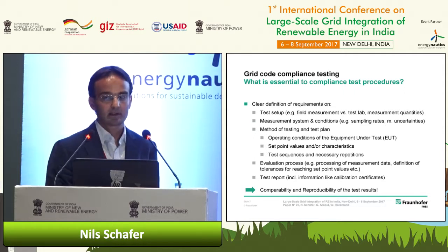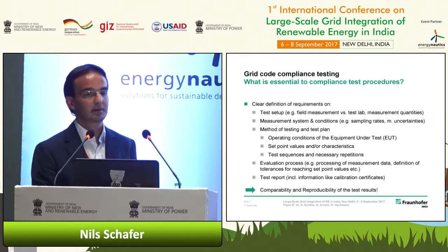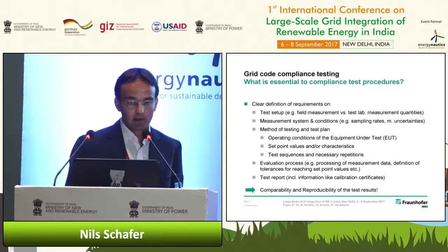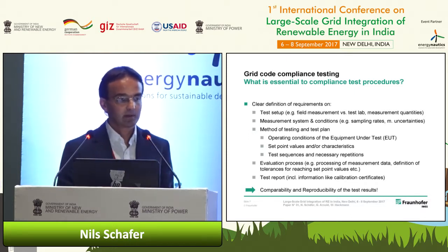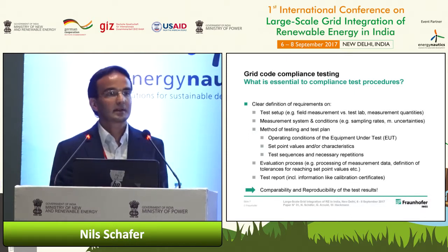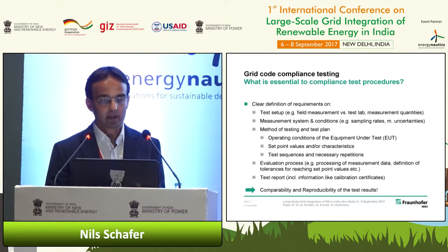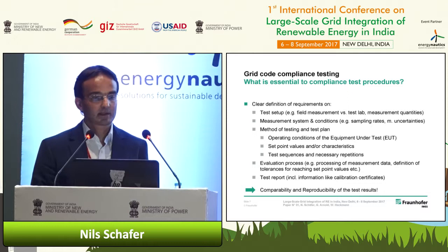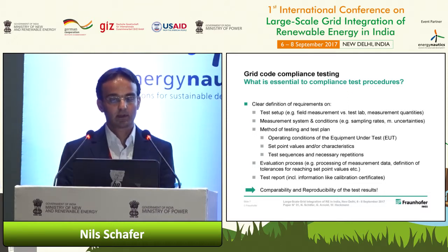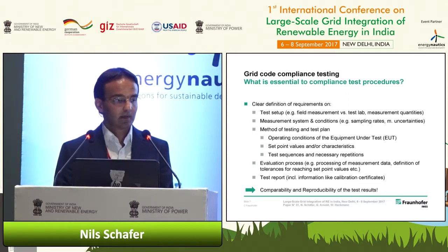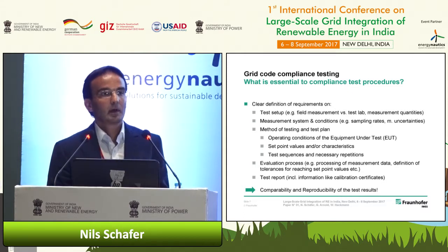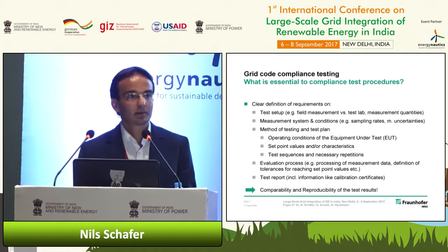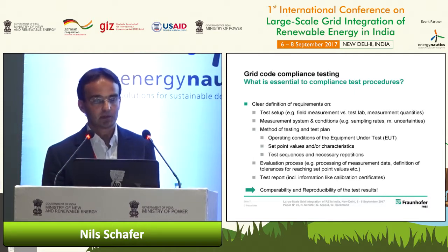The sampling rates and the measurement uncertainties you have to specify clearly. Then the method of testing and the test plan has to be defined. This comprises operating conditions of the equipment under test, the necessary set point values which are given to the equipment under test, test sequences, and also how often the tests have to be performed under which different conditions.